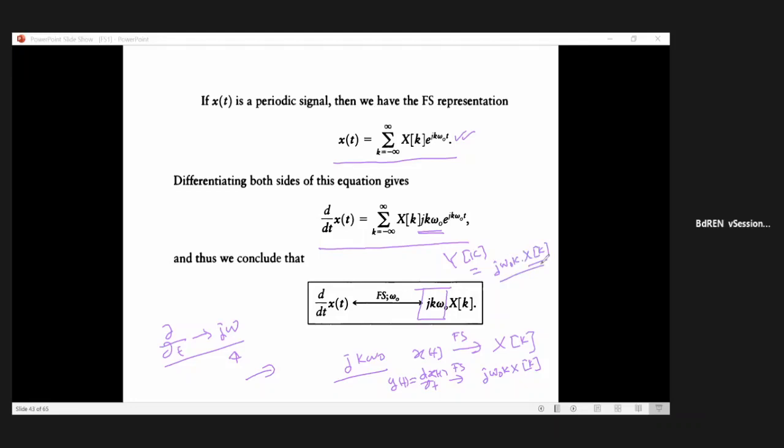Okay, this will help us to determine the Fourier series of some higher order functions. As we know, if we differentiate a higher order function in time, the order will be reduced. As a result, it will be easier. A triangular wave can be converted into a square wave. And you see that for a square wave, it is easier to find the Fourier constant than for a triangular wave.